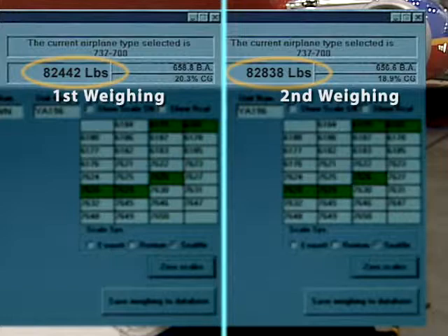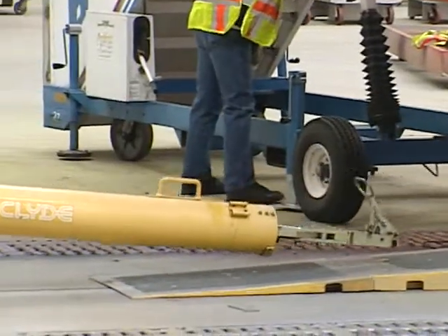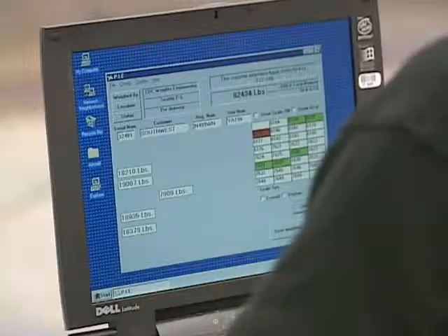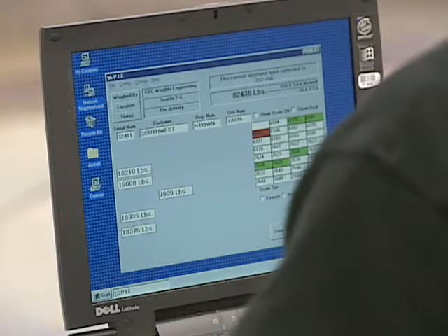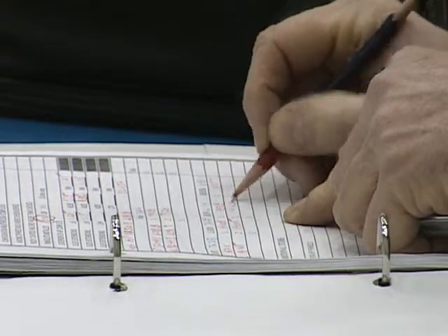If the second and third weights do not agree within tolerance, you must investigate and take corrective action. Errors in repeatability must be the result of either variations in environment, such as having the hangar ventilation system on, variations or errors in process, such as taking the reading before all non-airplane equipment has been removed, or intermittent problems with the weighing equipment. Repeat weighing until two successive weights and CGs do agree within tolerance, and record the first of the two readings. This will be the recorded scale weight and CG that provides the basis of the BEW and BEW CG.